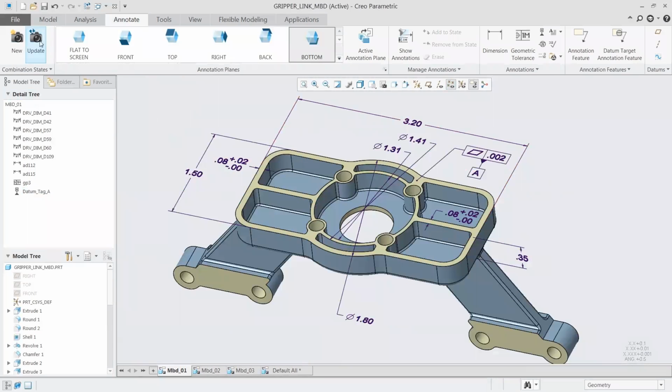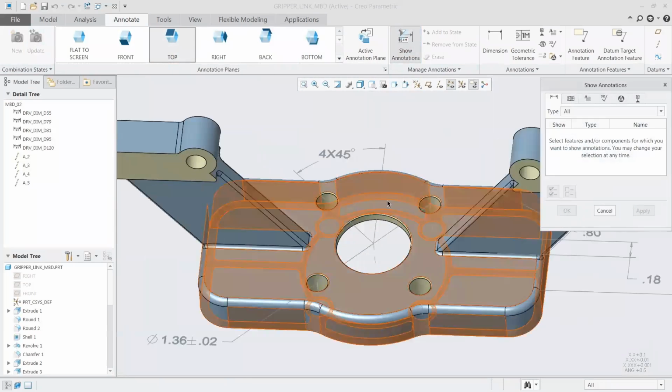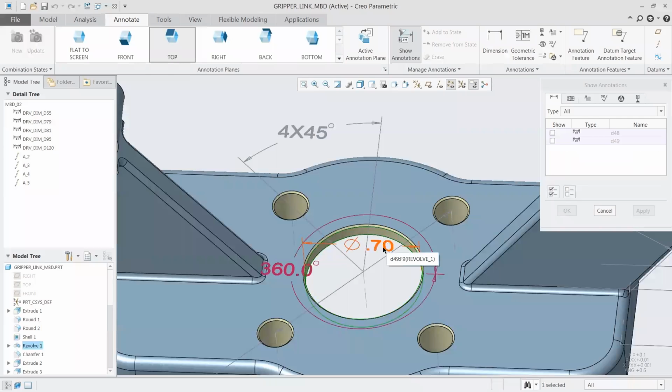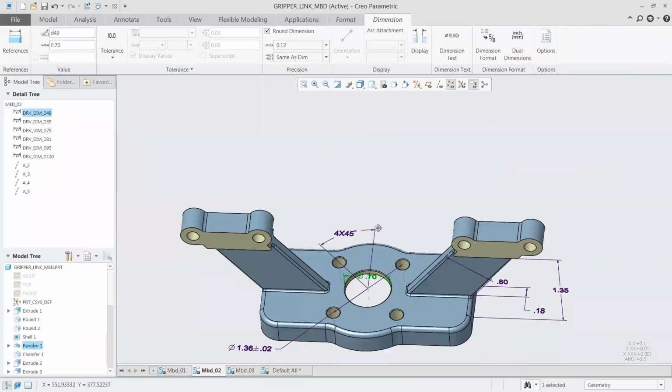For our second annotation, let's go to the center and show the annotation for this hole here. Okay. We'll just, again, select where we want it. It's going to put some of those annotations in there for us. We can drag and drop them. We can move them away. You'll see we also have the ability to just tell Creo to add a lot of these for us. And then if it adds it for you, you're able to go in and say, I want to delete these, I don't want these. So that's one tool that we see a lot of people use just to save some time.